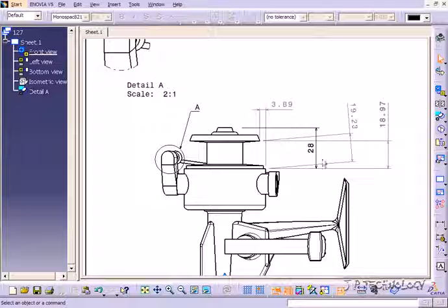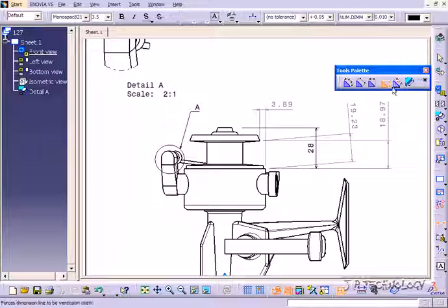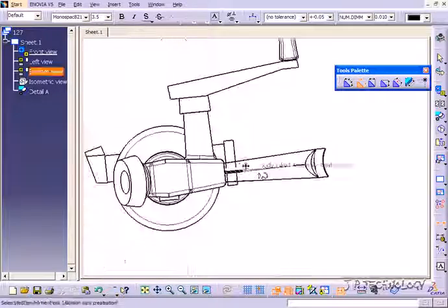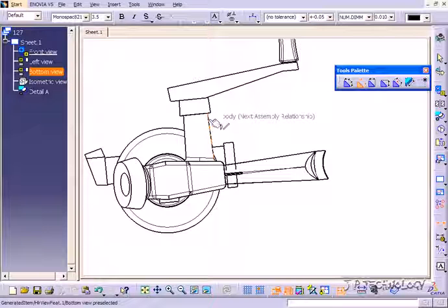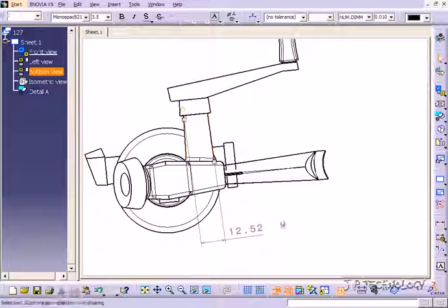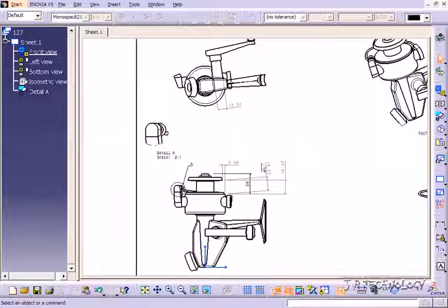So when you're going about it, you know what dimension you're looking for, and by using the vertical, horizontal, or forced dimension, you're able to force and impose those onto the drawing and get the results that you're really looking for. So with these, you're able to apply it to any drawing, any two lines, any two points. So you can just go around, click away at what you want, and you'll be getting your results. So that concludes our tutorial on the linear dimensions within Catia V5.